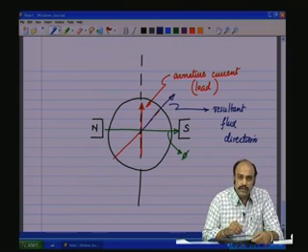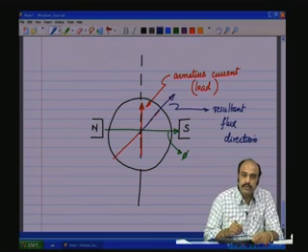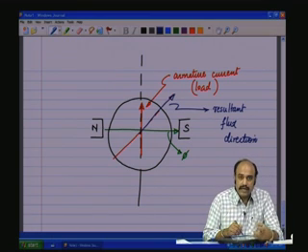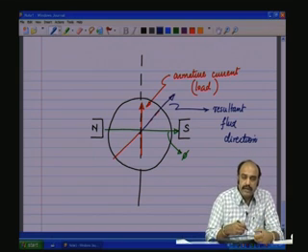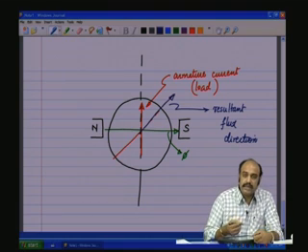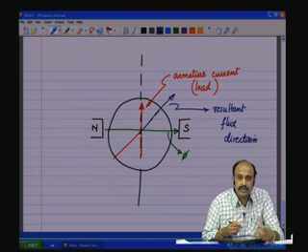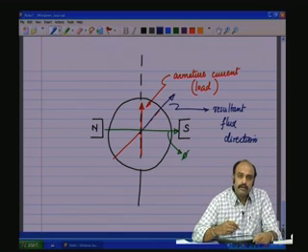And that voltage which is getting induced in the coil due to this armature current produced flux will short circuit the coil and produce a huge short circuiting circulating current, and therefore I square R losses. And as a result, when the brushes are passing over that coil, there is a current flowing through it, and then there is an inductive reactance in the coil, because the coil is inductive in nature. It is trying to suddenly break the coil and there a huge spark results. So, the sparking will also be very high in the brushes, and the brushes will go bad much more quickly.